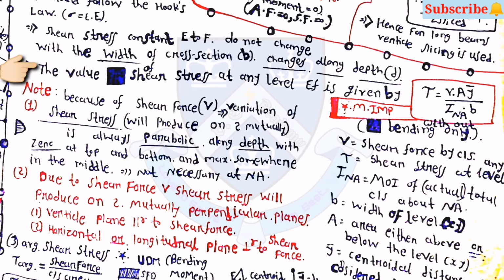Here the value of shear stress at any level is given by tau is equal to V A y bar upon I NA into B. Note that because of shear force V, the variation of shear stress is always parabolic along the depth, with 0 at the top and bottom and maximum somewhere in the middle, not necessarily at the neutral axis.